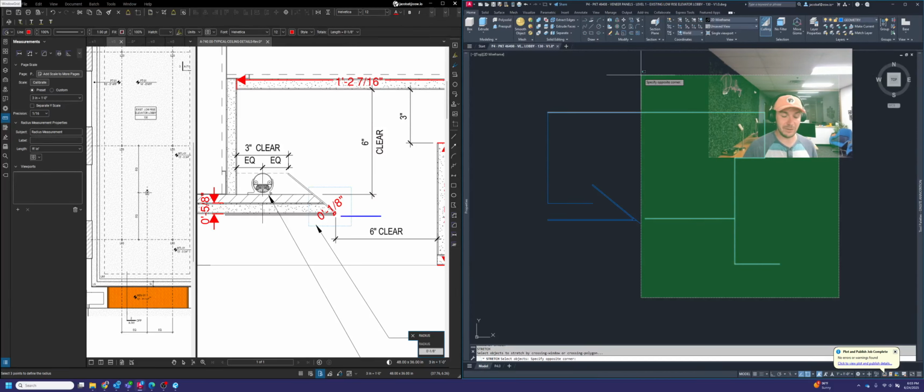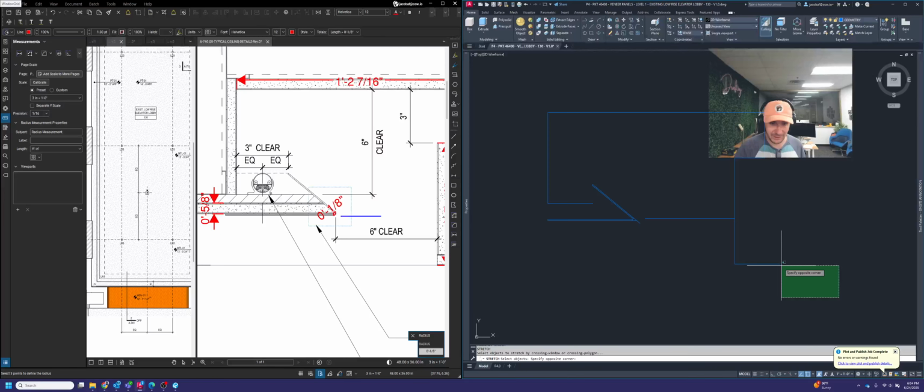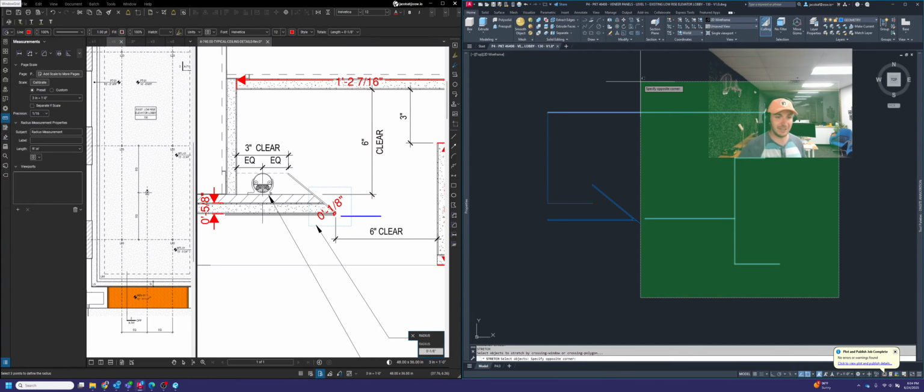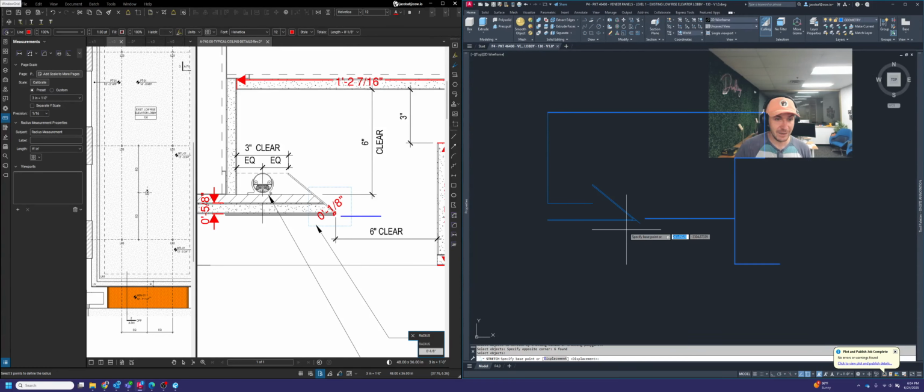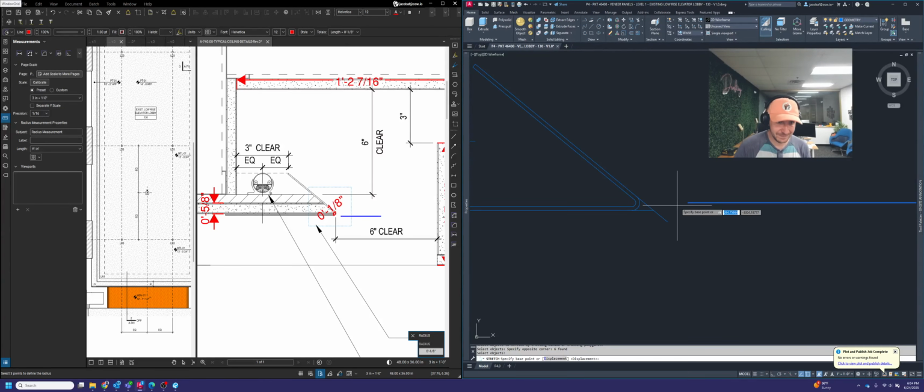As you notice, one other thing that I like to do is select outside of that area in the blank space, because trying to get that just spot on, like trying to click this point and move up to here, is probably not realistic, and it's going to waste time. So it's better to go about it this way, where you just select all of those lines together, and you click outside of the area that you're trying to select, kind of like this. Anyway, once you have that done, hit enter, and then it's going to ask you to select a base point, in which I'm just going to grab this point here.